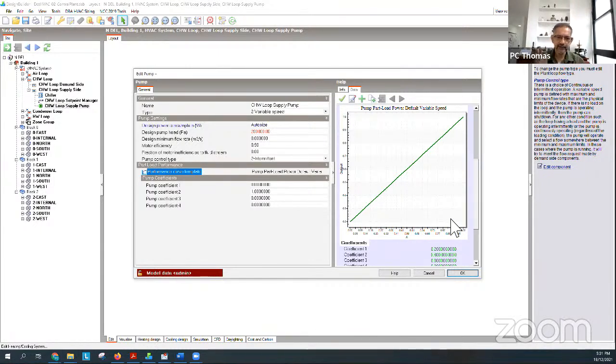Now, the reason I say this is fine is it's not the pump curve that you're interested in. It's the pump system curve, because the pump is pumping through a piping system. We haven't designed the piping system right now. We really don't know that unless somebody works through the number of bends and the length of pipe and the pressure drop across the chiller evaporator vessel and so on and so forth. Okay, so typically using a linear curve is a reasonably good conservative value. So I'm going to leave that over there.